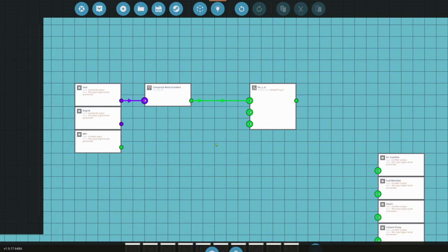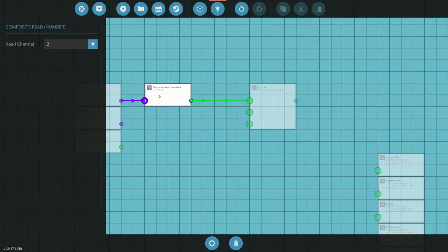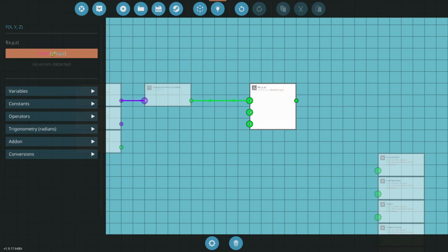And I'll tell you why I do it this way. What this is going to do is it's going to take your X, which is your 2. Now, your 2 value can go from your WS from -1, which is going to be maximum brakes for us, and it could go up to a maximum value of +1. So if we take our 1, which is our maximum, our foot is all the way down on the floor, and we multiply it by our maximum RPS, for example, let's say that's 20 RPS, when we press our accelerator pedal all the way down, we ask the PID to give us the maximum RPS that we want, which in this case will be 20 if we put that number in. If we change it to 15, it will then change us to 15. So that's how we're going to do that.